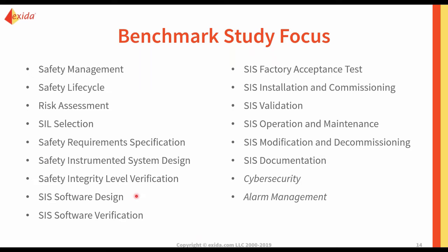SIS application verification. So not only having clear documented requirements for the instrumentation, but also for the application programming that's run on that equipment, and ensuring that you don't have the potential for any dangerous failures that have been introduced based on the application program the controllers are running.